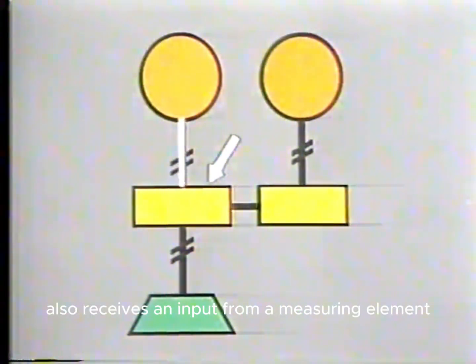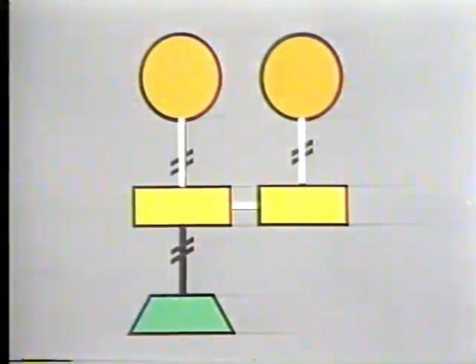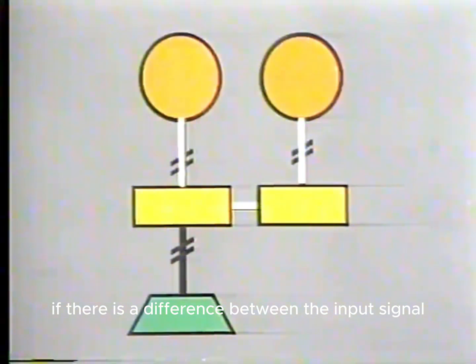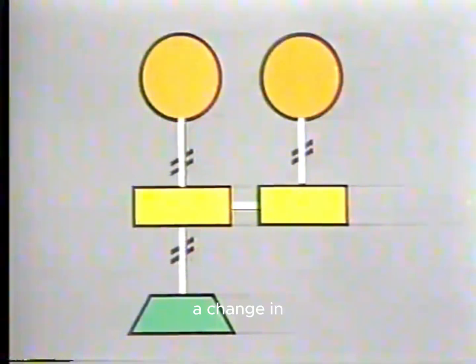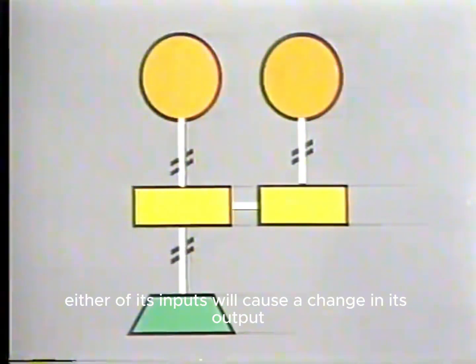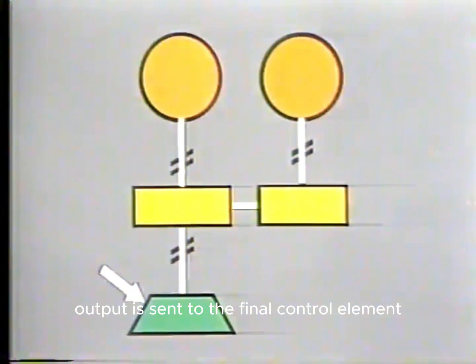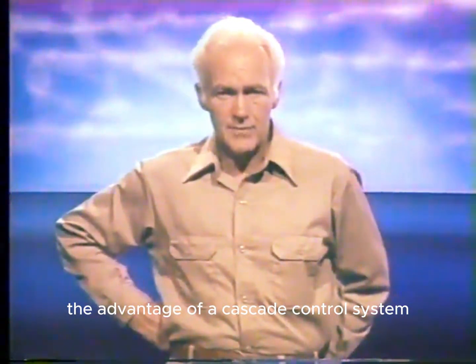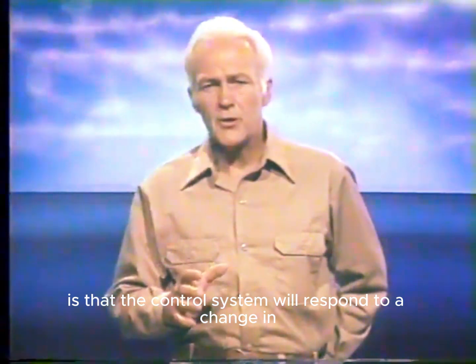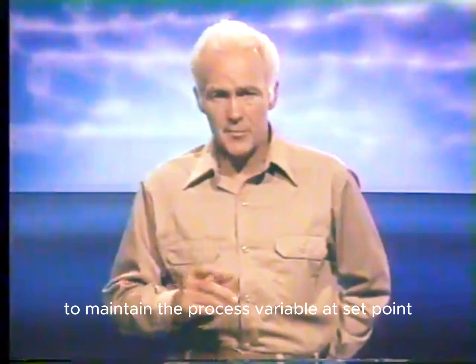This controller also receives an input from a measuring element, which it compares to its set point. If there is a difference between the input signal and set point, the controller's output will reflect that difference. A change in either of its inputs will cause a change in its output. The change in output is sent to the final control element to return the process variable to set point. The advantage of a cascade control system is that the control system will respond to a change in either of the monitored variables to maintain the process variable at set point.